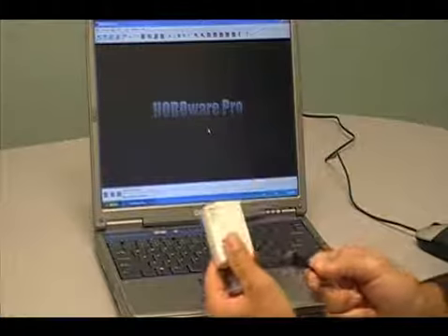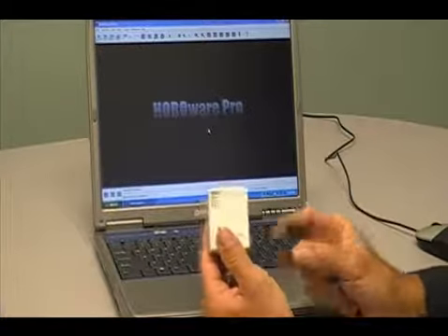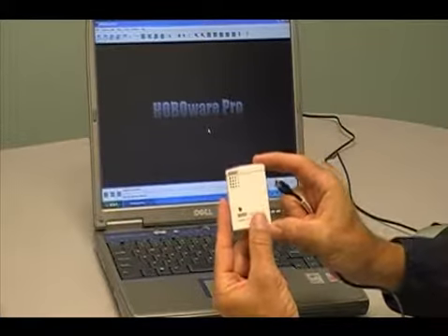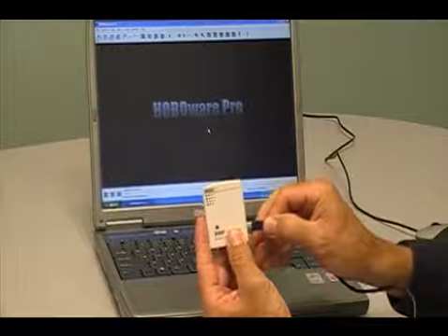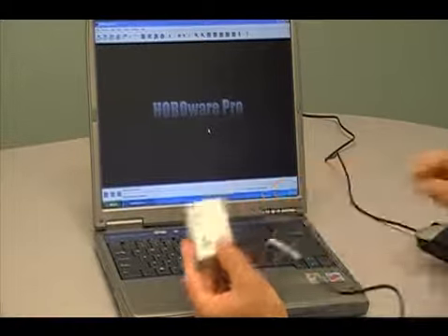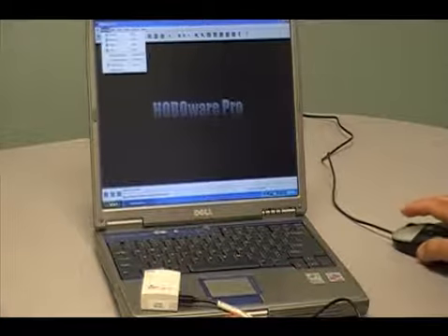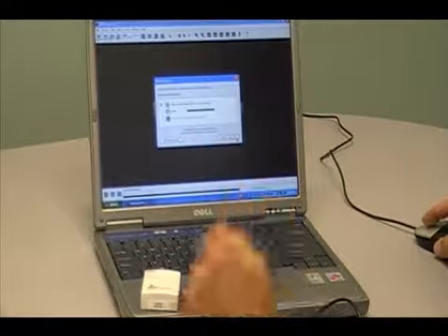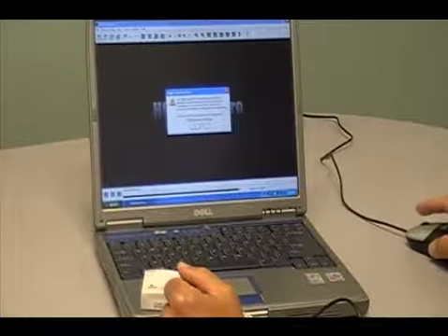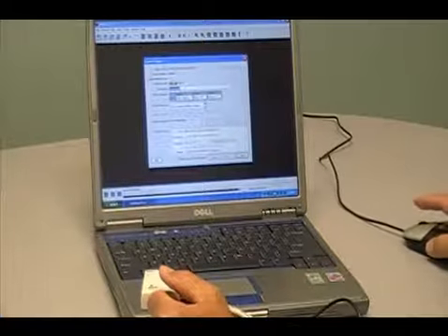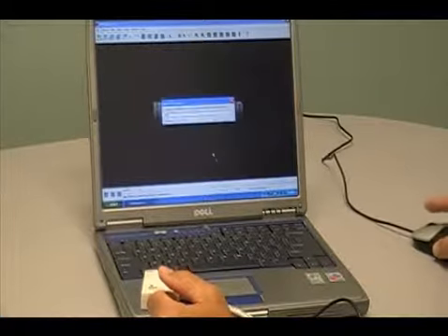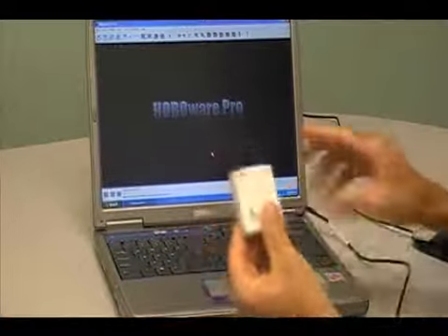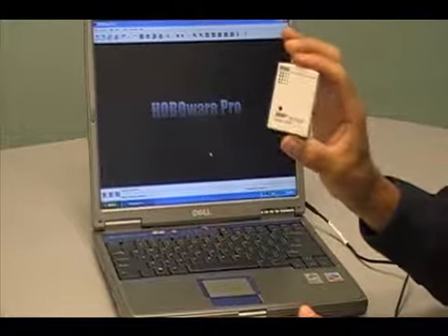The first step in doing a machine runtime study is to launch our data logger. Today we're going to be using a U9004, which is a motor on-off data logger. We simply take the USB cable, plug it into the USB port, and launch it with the software, HOBOware. A couple of clicks. The software sees the logger, tells us the status of the logger, that the battery is good and so forth, and we launch it. Now we can unplug it and the logger is ready to go to be mounted on the machinery.